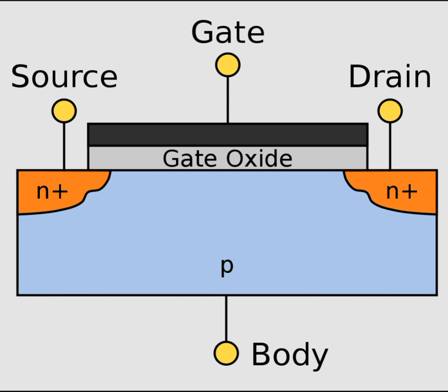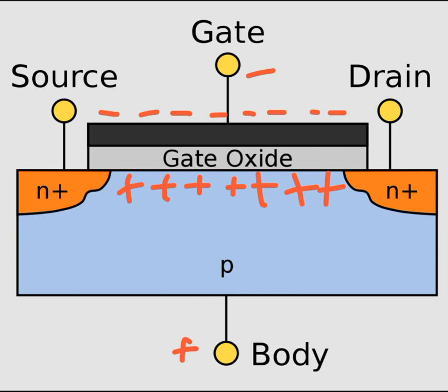Now we have seen two situations. Now situation number 3, let's say you apply a negative potential to the gate and the body is tied to the positive potential, so it's just opposite polarity. With that, you have lot many negative charge carriers on top of the metal, on top of the gate, and because of that you are going to attract lot many positive charge carriers at the gate oxide and the p-type semiconductor interface. Interface is this line. So you have again an electric field created with the direction of electric field lines and electrostatic force as shown.